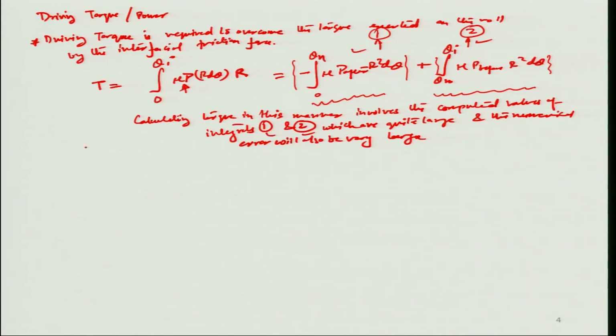So let us look at some kind of an alternate strategy, by not really directly calculating what is going to happen by the friction on the rolls, but to consider the horizontal equilibrium of the deformation zone of the strip to calculate the torque with probably more accuracy than such a large numerical error which is involved in the last step here.